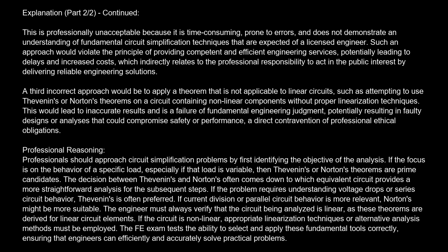Professional reasoning. Professionals should approach circuit simplification problems by first identifying the objective of the analysis. If the focus is on the behavior of a specific load, especially if that load is variable, then Thevenin's or Norton's theorems are prime candidates. The decision between Thevenin's and Norton's often comes down to which equivalent circuit provides a more straightforward analysis for the subsequent steps. If the problem requires understanding voltage drops or series circuit behavior, Thevenin's is often preferred. If current division or parallel circuit behavior is more relevant, Norton's might be more suitable.